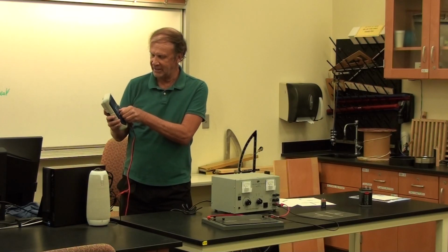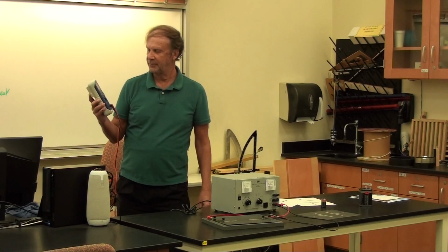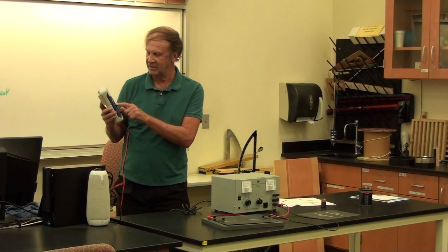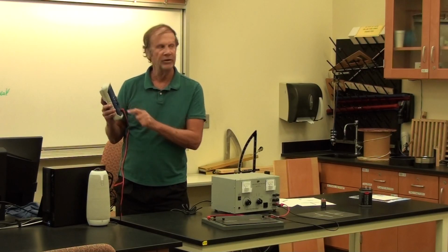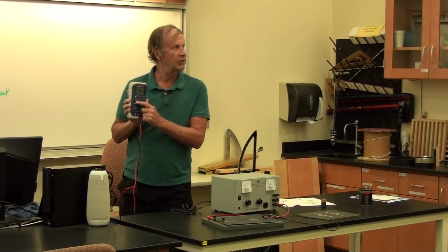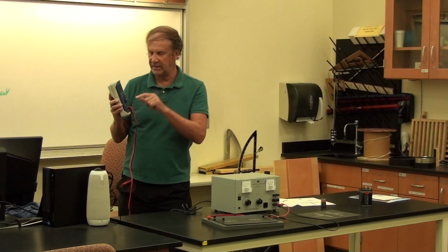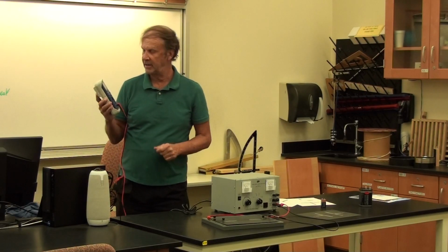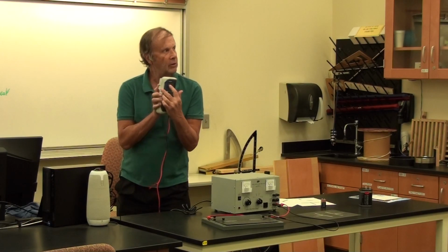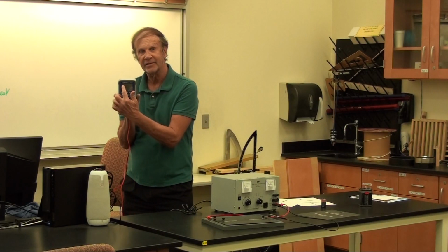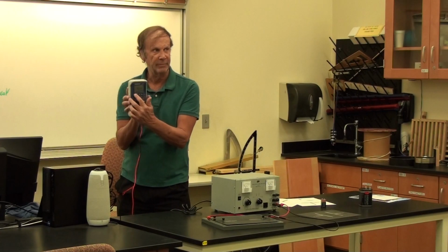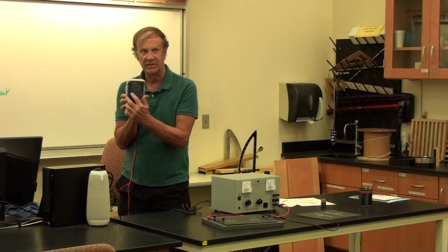So all you have to do then is move this to the volts here, not millivolts, because we're measuring more than millivolts. So just the regular voltage setting, but not the one with the wavy AC line. It depends on which meter you get. One will have the wavy AC line and a flat DC line. You can always tell what mode you're in with this little display. It'll either say DC or AC. If it says AC, then you need to hit this magic little button here, and that'll change it to DC.